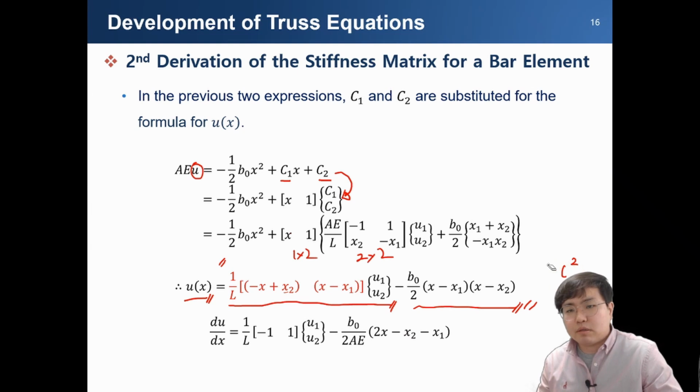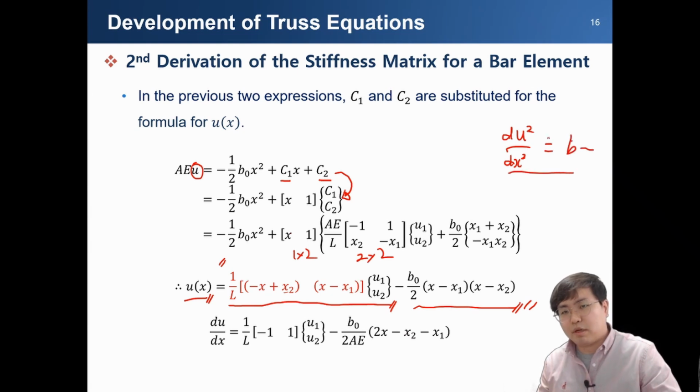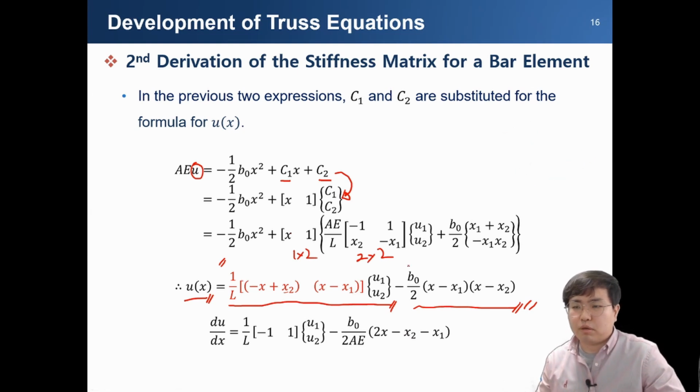It is big. However, when you neglect the body force term, here it contains x square, but here there is no x square term. It must always become 0 without the body force term. That's why in the previous slide I mentioned that this becomes zero. Without those terms, we always obtain zero. So if you want force equilibrium, the body force term always expresses the second derivative, a quadratic form, and then the stress or strain relationship is expressed by a linear form of x. So anyway, we obtain the exact displacement form.